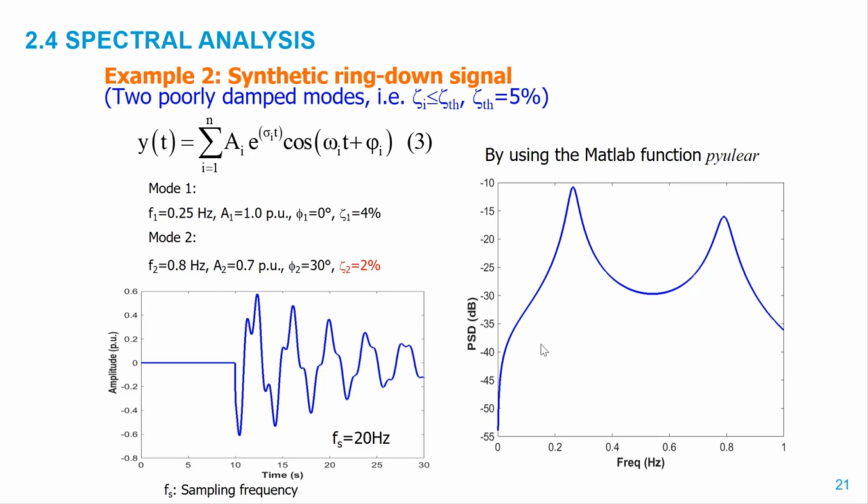And now we can see the two dominant oscillations clearly there around the frequencies that we theoretically defined when we created the synthetic signal. So in this case, we can conclude that by having some signal and doing the power spectral density calculation by the Yule-Walker method, we could at least estimate the dominant frequencies in the system, and how this can vary in time can also be done. We will start windowing the signal records over time and then computing the power spectral density, and then we see the variation of the spectral density over time. That will probably be a three-dimensional plot. We understand a bit how dominant oscillations are varying in time, so how their frequency parameter is changing.